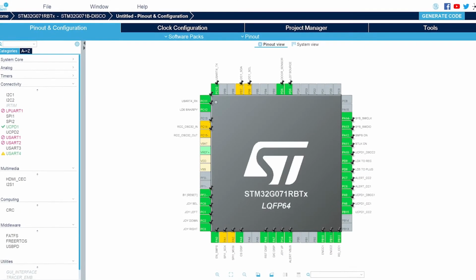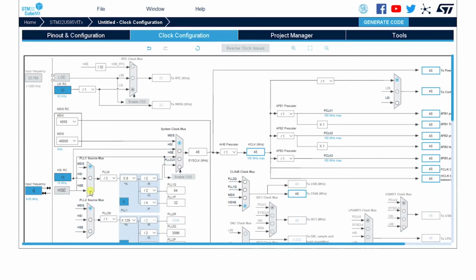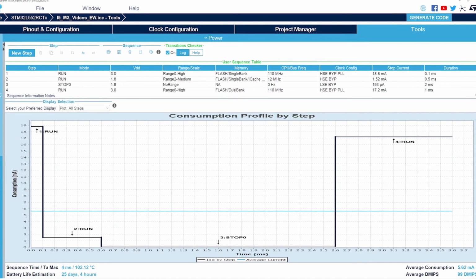It's great to think about what developers like the most about our existing CubeMX features: how they can optimize hardware design with our graphical pinout preview of the microcontroller, how developers can create and enable the UART peripheral in less than 5 clicks, how it's easy to solve the internal clock tree. For low power applications, we have a tool to estimate low power consumption, which we call Power Consumption Calculator. We let you generate a C project for your favorite IDE, and we let you decide between fast time to design and higher code optimization with HAL or LL drivers.